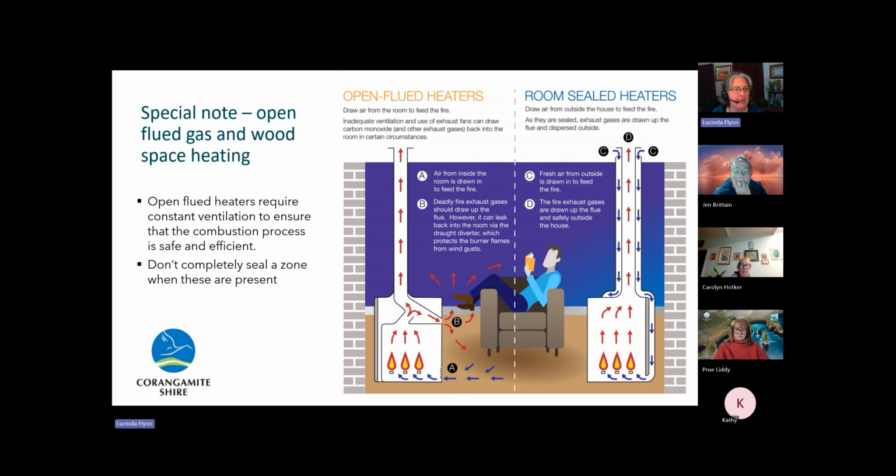I want to make a special note of draft sealing in relation to the safety of the air we're breathing. The rental standards are actually that you are not allowed to draft seal a room that has an open flue heater.